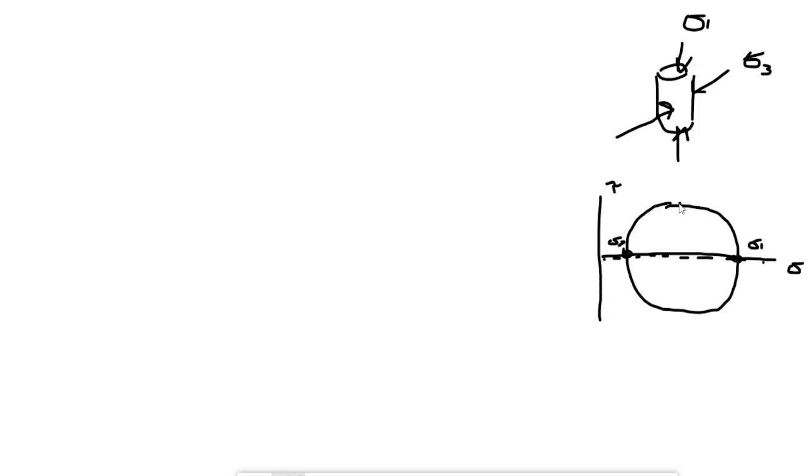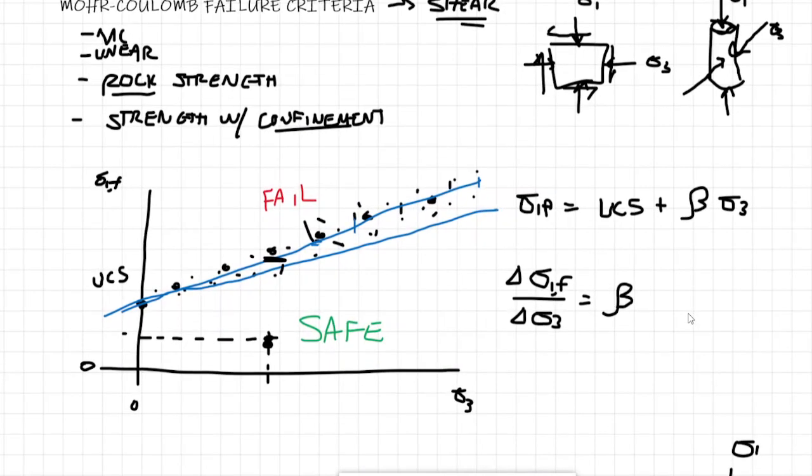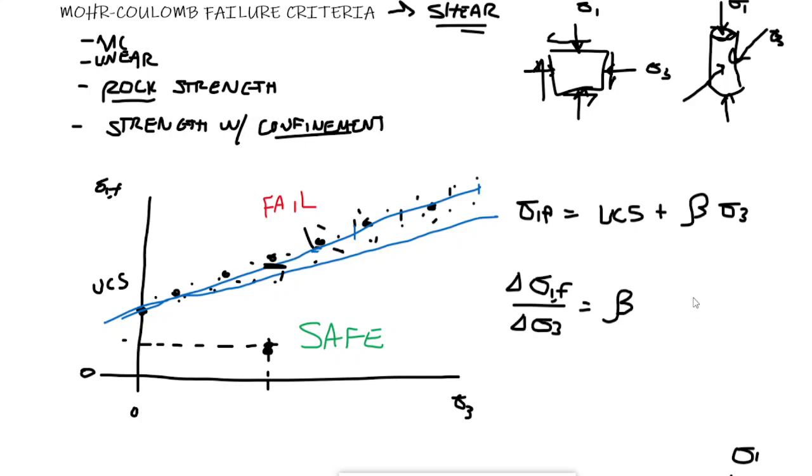And remember, at those points, there's no shear stress. But as you change the orientation, this is the important thing. When we look at this data up here, it's a little bit limiting, and it doesn't keep your brain thinking about it in a very realistic way if you're just thinking about it in terms of principal stresses, because so many times what you have is them changing and reorienting themselves around discontinuities, around fracture planes within a rock or rock mass especially, right?